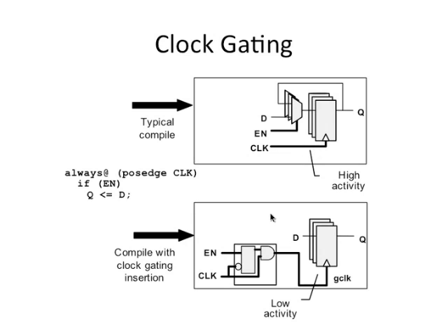The other way of implementing this is what is called clock gating, where you gate the clock. So this G clock input changes only when enable is high. Otherwise it doesn't change. So when it doesn't change, Q retains the old value. Q changes to the new value only when enable is high, right? So this is basically what is clock gating.